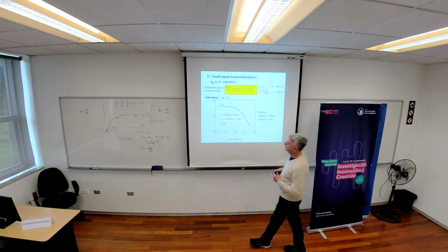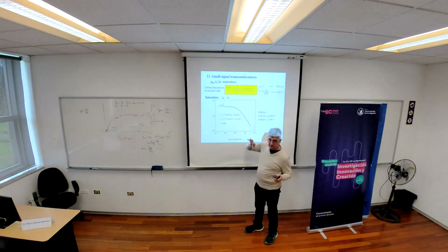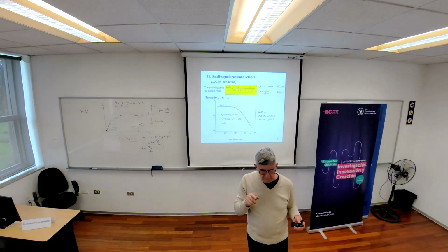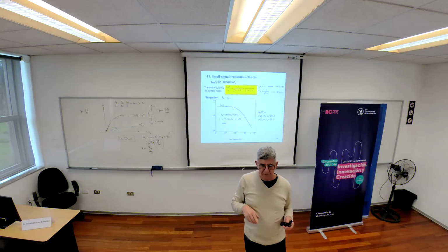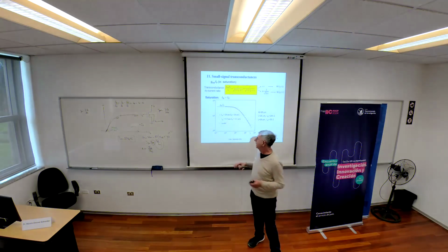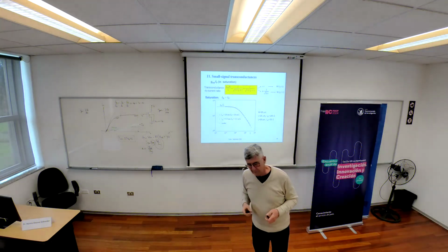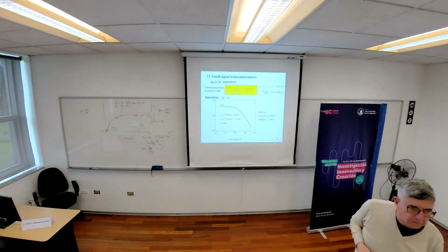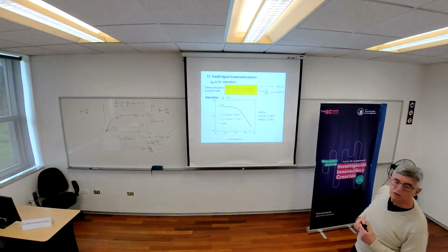There is a rule that we apply: the minimum channel length is around 40 times the oxide thickness. This is a rule of thumb, approximate. It's not exact, but it's an approximation for the calculation of the minimum channel length.